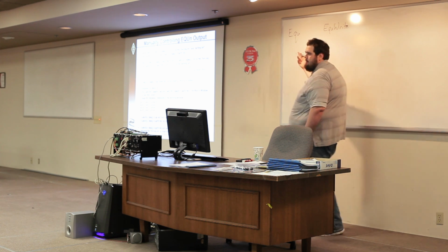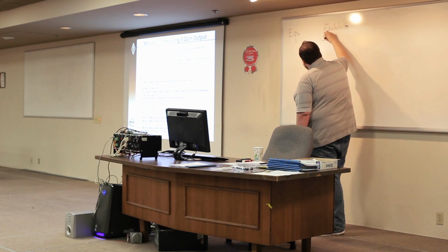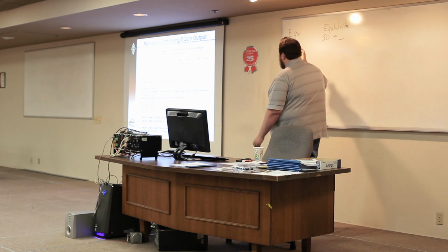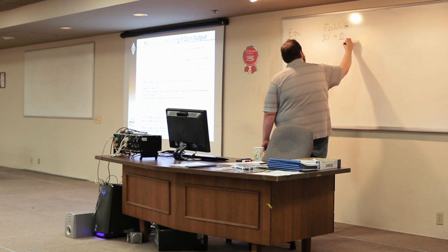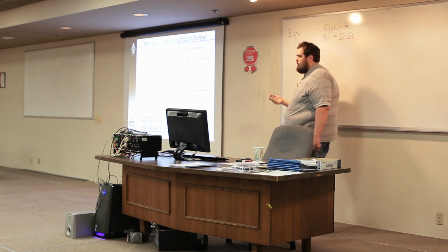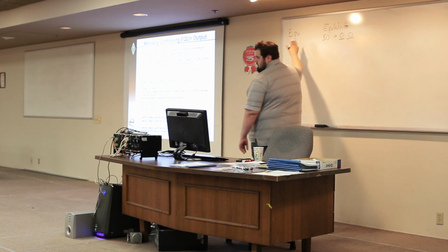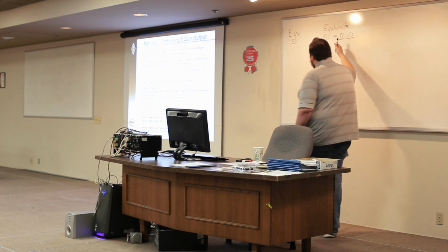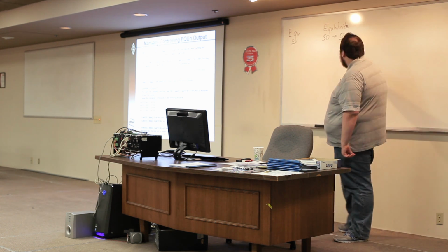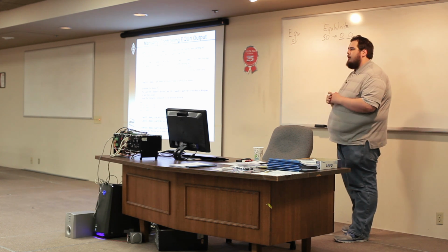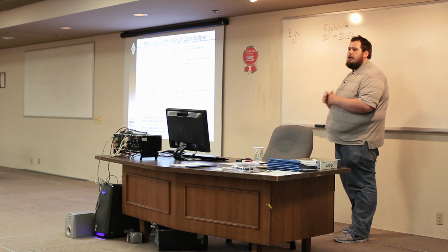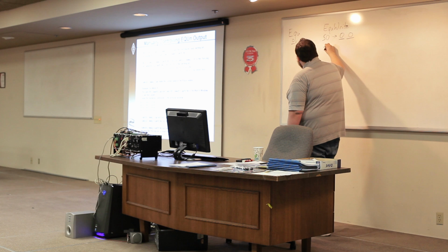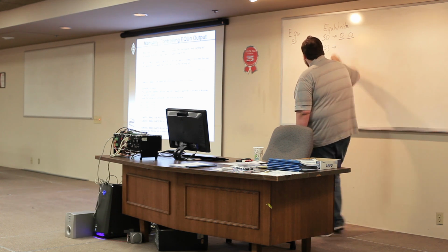EQU write, if I put a value of 0 in here, that translates to a writing bit, as I call it, of 0 and a forcing bit of 0. If this is the case, if EQU starts out at a value of 0, it's going to remain at a value of 0. Because, first of all, our writing bit is 0, but that doesn't even matter. Our forcing bit is 0, which means we are not going to force any value into EQU. We're not changing the value of EQU. Now, if we instead put $3 here, that's 1, 1.